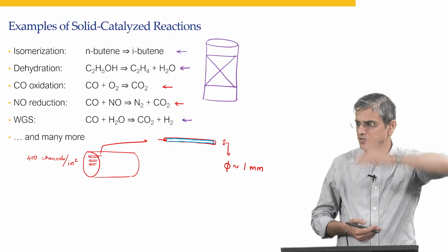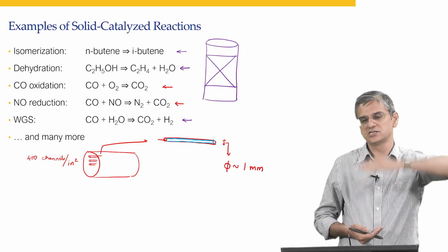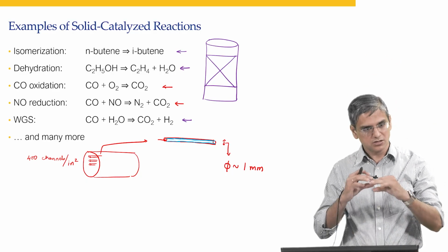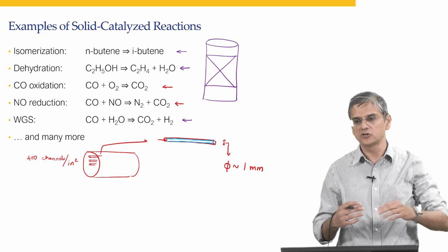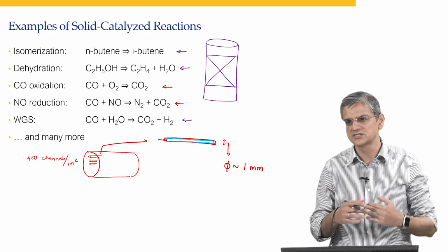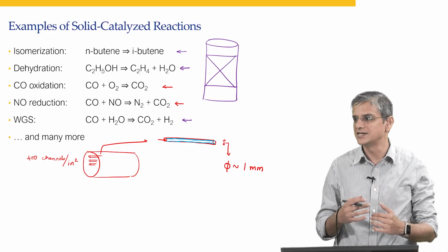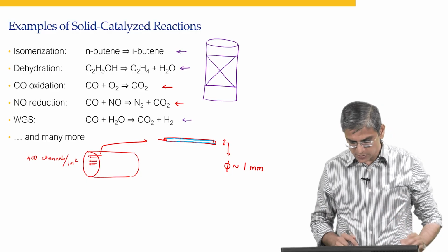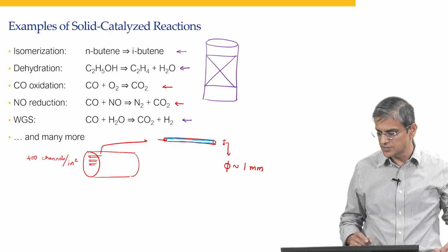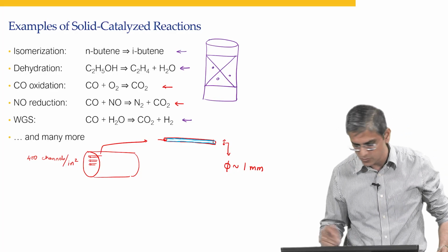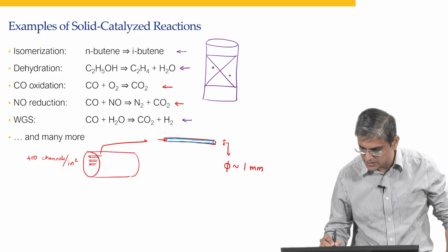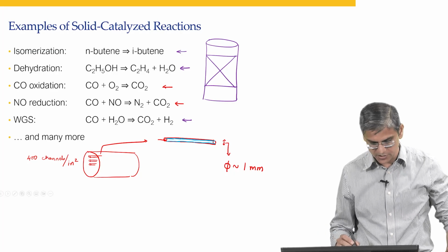Okay. If for example, this fixed bed reactor is say 2 stories tall, then the bottommost pellets will have a lot of weight coming from the top and they can get crushed. So, there will be a lot of structural elements to ensure that that does not happen. Okay. So, that is what a fixed bed reactor consists of, but as far as we are concerned, there are going to be catalyst pellets present within the reactor, and those pellets are where the catalyst is present.